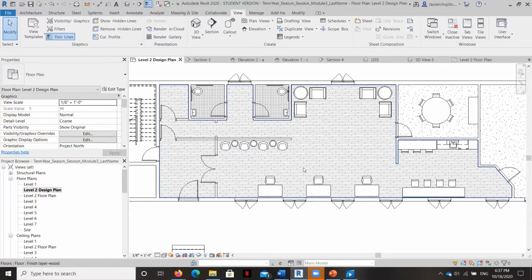For example, in our wood floors here, wood floors need an expansion gap because wood expands and contracts in humidity. And so there's always about a quarter-inch gap between the wood on the floor and the walls. And so that needs to be covered up with a baseboard. And baseboards are also used to protect the wall against any sort of damage that might happen from mopping or vacuuming and things like that. So they're a really important part of any space. And so that's why I wanted to teach you how to create them here.